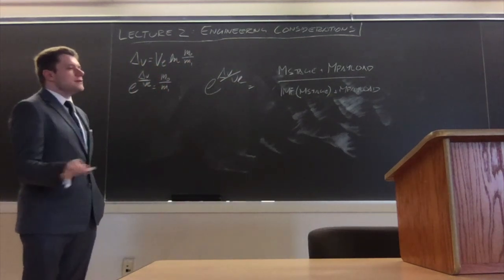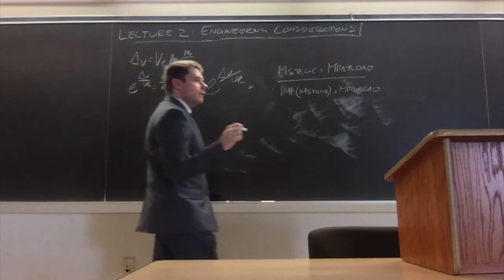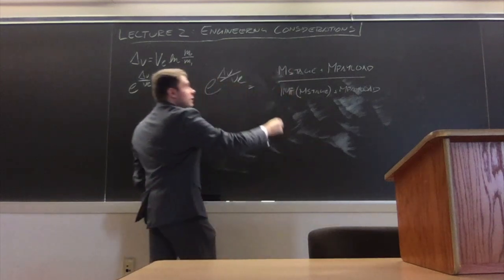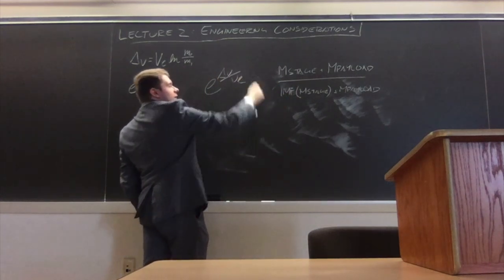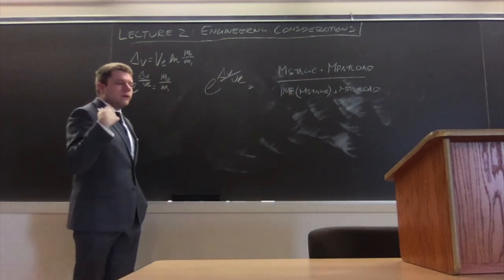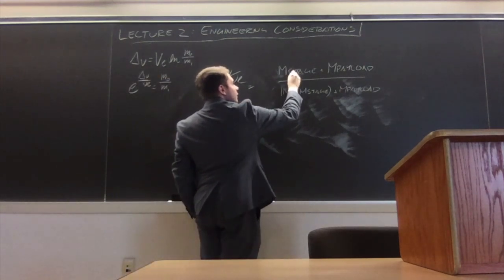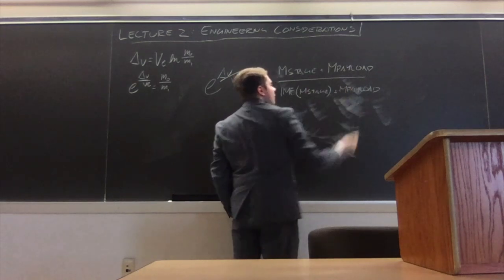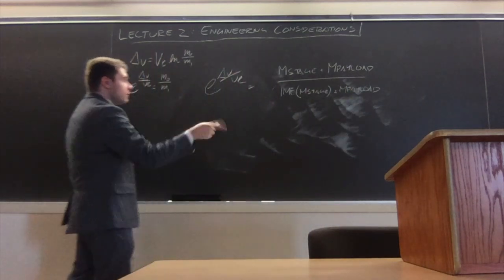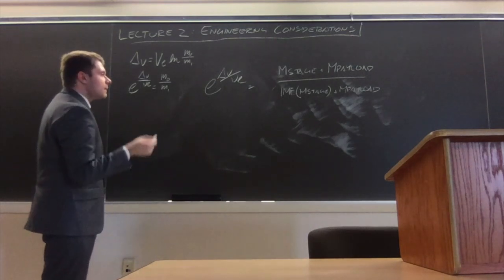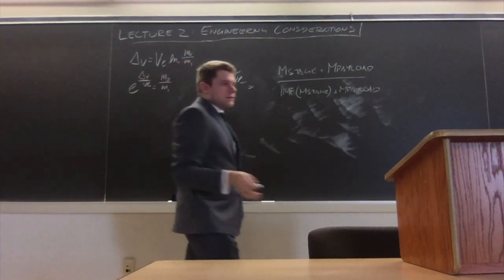Because that's our consideration, that is our setup problem here: we want to determine, for a given payload mass, which is what we can totally control, given our delta V and our effective exhaust velocity, all factors that we know or we can calculate or we can approximate, we need to put those terms in and come up with reasonable numbers for our stages, with the realistic consideration of the stages themselves having inert mass to come with them. So we can rearrange this very simply.